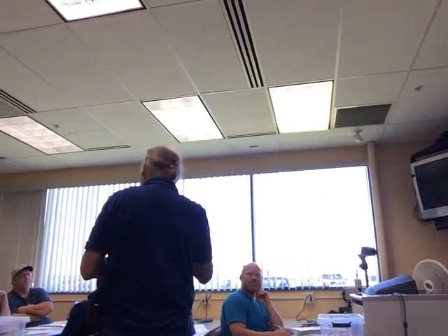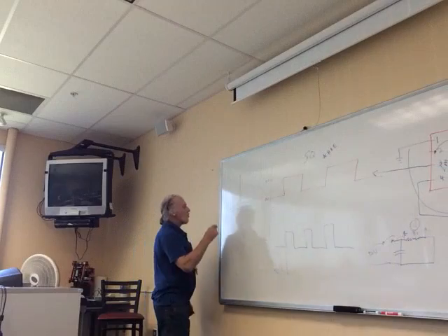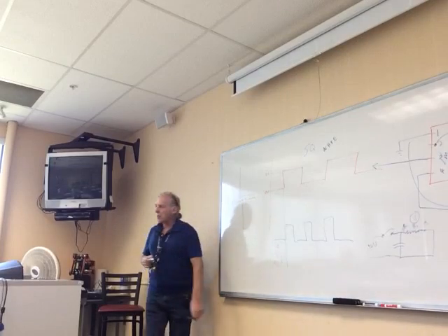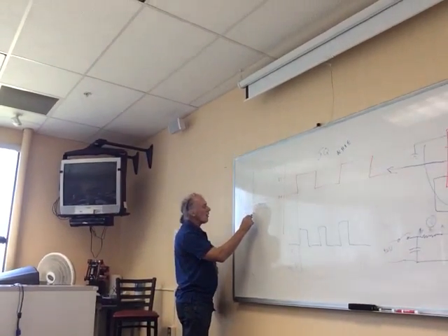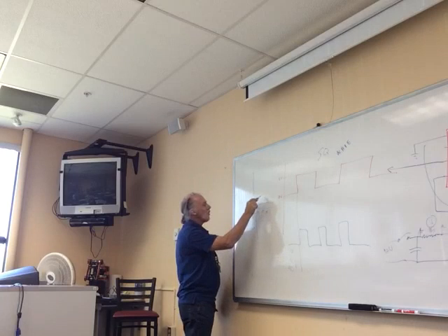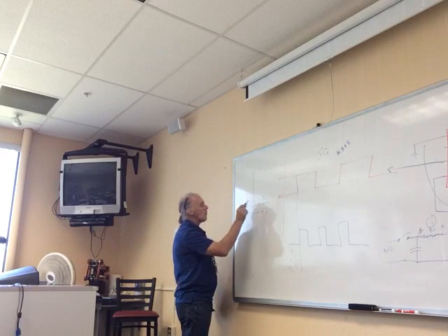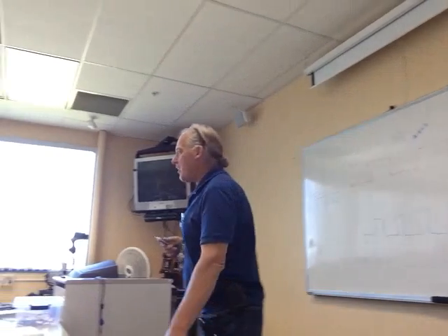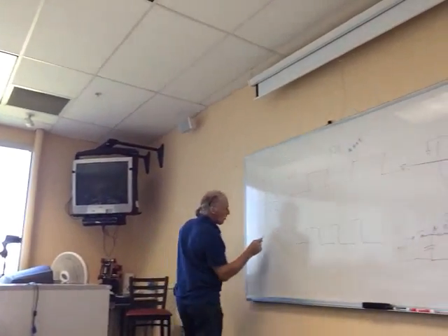Some of them were electrolytic, so they had a little chemical in there so that they could store more electrons. What happens is we have a plus plate and a minus plate, and when we charge the capacitor up, we just put all the electrons here. And what does that do over on the other side? Well, it is deficient of electrons on this side, so it makes it positive. Okay? So how do I do that? Well, I just take a power supply and I put it across the leads right here.